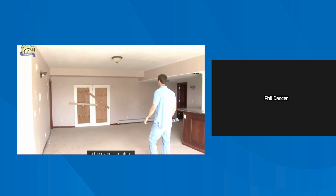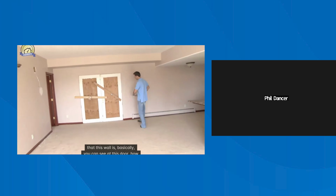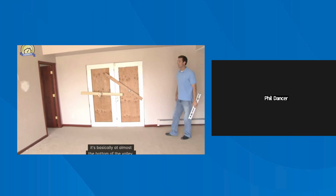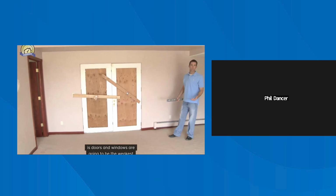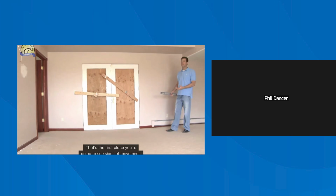Which again is going to cause problems to the upstairs and the overall structure. You can also see coming back through here, at this door, how it's basically at almost the bottom of a valley if you look at it. The reason for that is doors and windows are going to be the weakest points on a foundation. And so that's the first place we look for cracking. That's the first place you're going to see signs of movement.